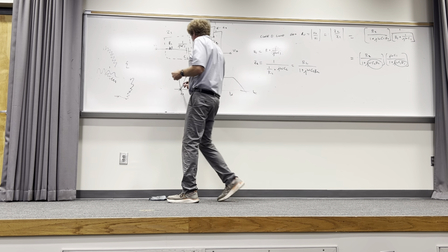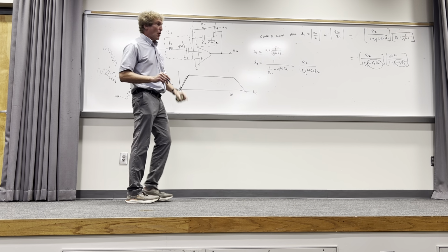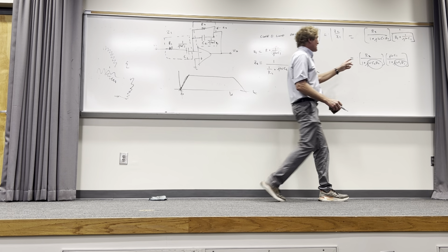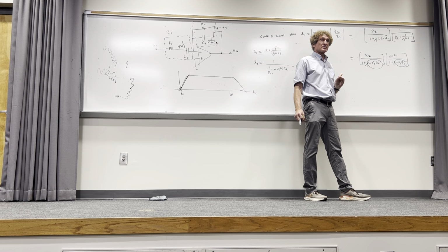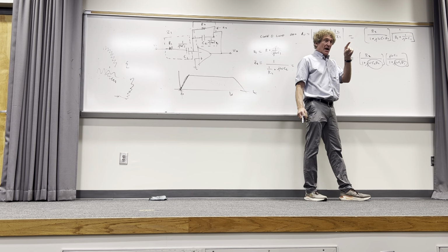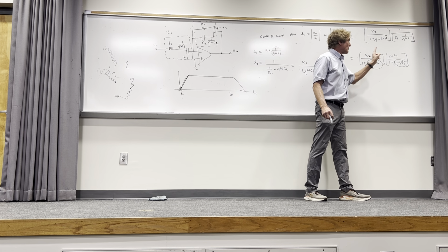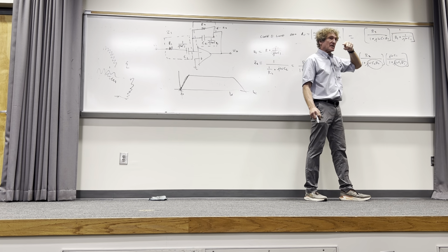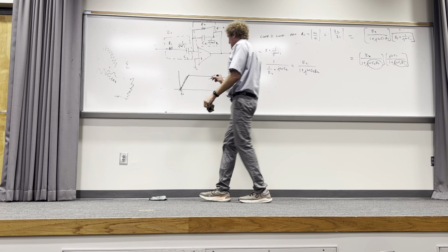That would be down here. I'll fill in the actual values in a second. But something happens. All of a sudden, one of these two values, just listen now, goes to 1, so omega goes up. You all follow me? At that frequency, these things start going down at 20 dB per decade. This was going up at 20 dB per decade. They cancel and it's flat. Listen to me now. So it will be flat, like this.